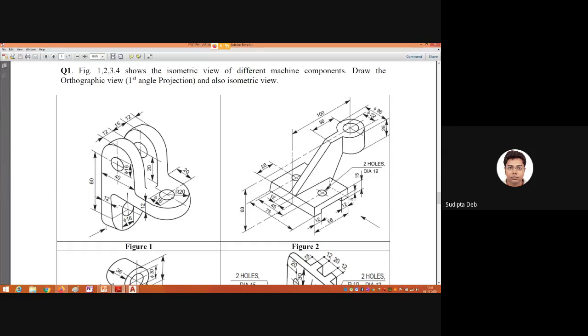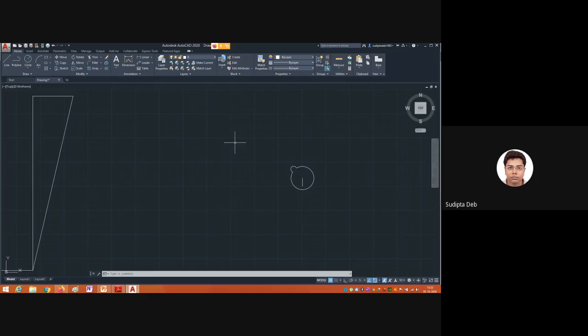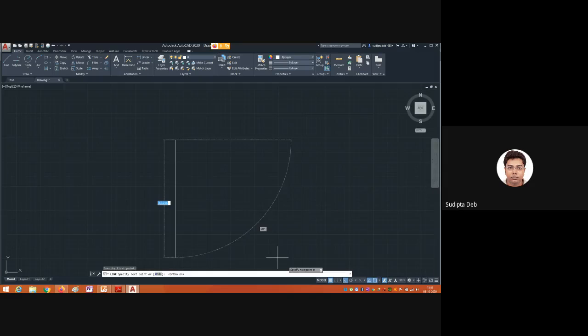Let me draw, so it will be clear. I am taking AutoCAD; 60 is given. I am going to draw a line first, sorry, 60 distance, 60 millimeter. Let me erase all. First command is line. Ortho mode on, distance is 60. Enter.